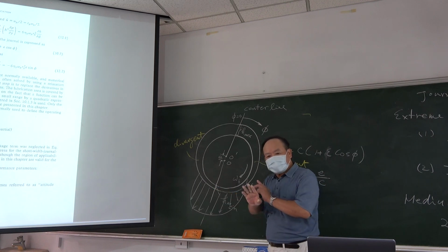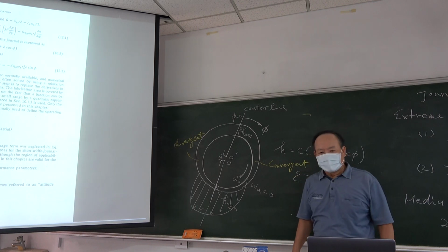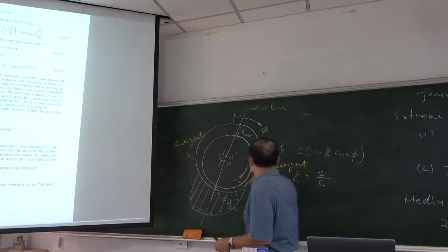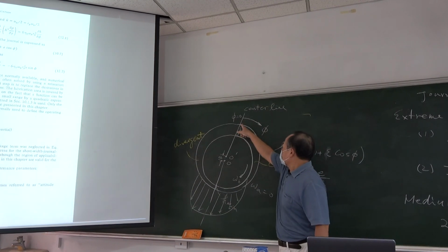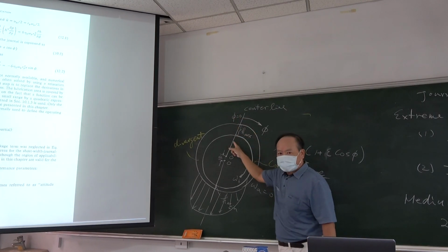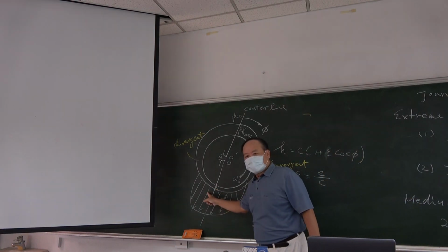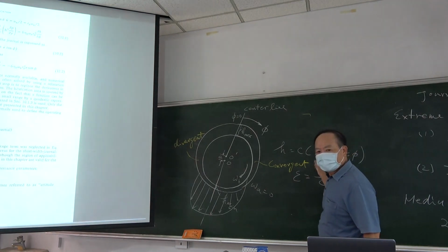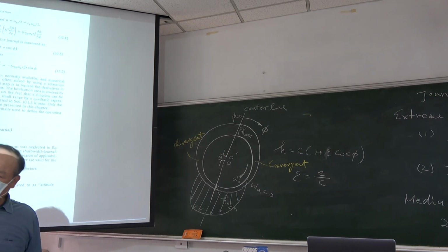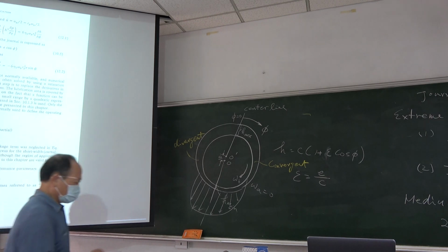Okay, so it's not a spelling error, or miswriting. No, this depends on your phi. Which point is phi equal to 0? You can start from the maximum film thickness. In this case, this is plus. If you start from the minimum film thickness, then here you have a negative value. Okay? So it's not wrong. This depends on your definition for the phi equal to 0 position.